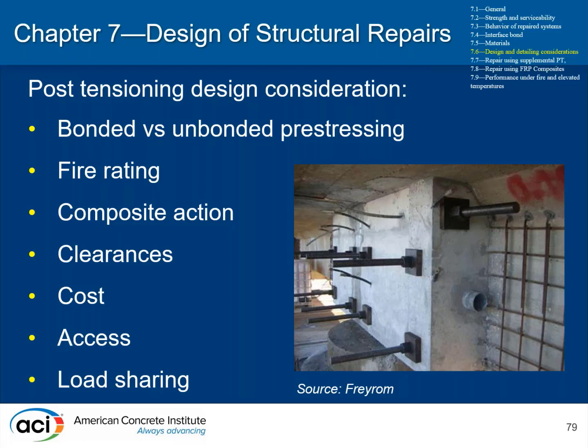With regards to repair included in post-tensioning, external post-tensioning, obviously fire rating of any external post-tensioning comes into play, as well as evaluating how that additional post-tension could put additional stresses on a member, such that design and analysis should be conducted to evaluate those conditions to make sure that the external post-tensioning is working as intended. So it's an effective method for repairing for sure, but as in all considerations, just ensure that the loads being imparted by the additional post-tensioning are compatible with the structure.